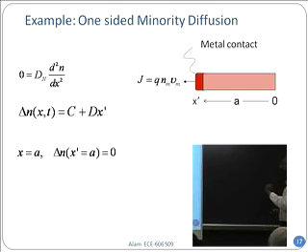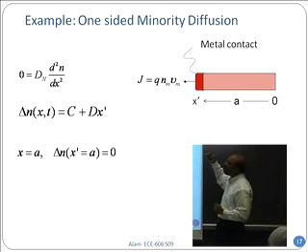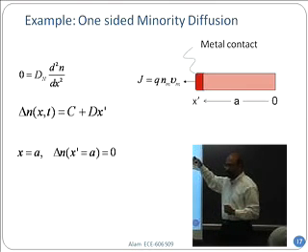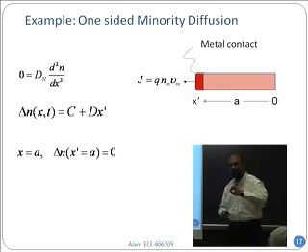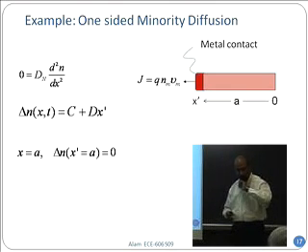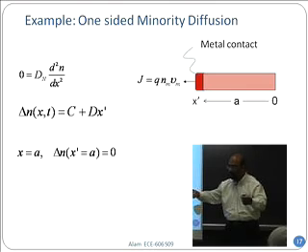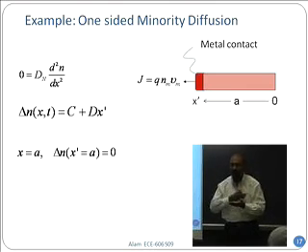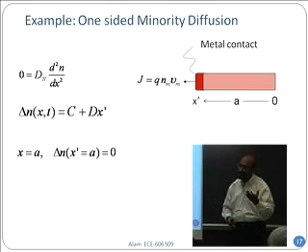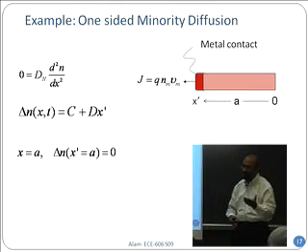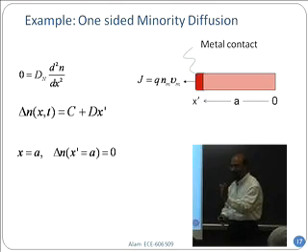The reason is, once the electrons get out of the semiconductor and into the metal, the metal has very high mobility. Electrons go very easily, right? When you have a copper wire and put a voltage in it, doesn't a lot of current flow? So electrons have very high mobility and very high velocity within the metal. Now, if it has a very high velocity, in order to support a certain amount of current, how much delta n would you need?